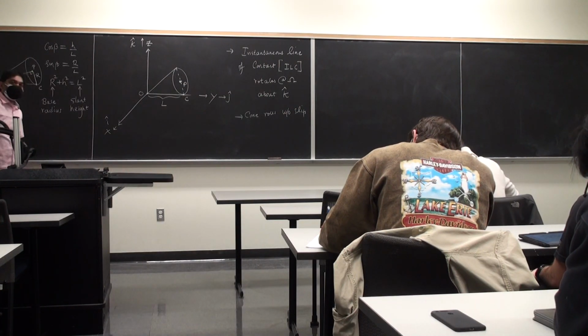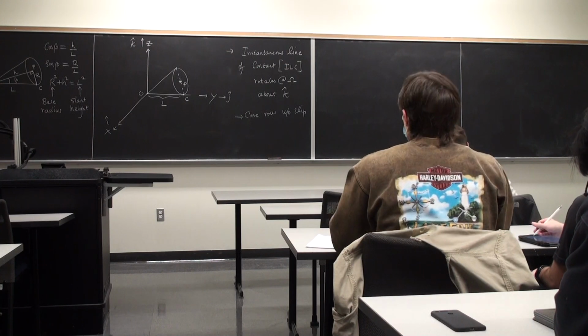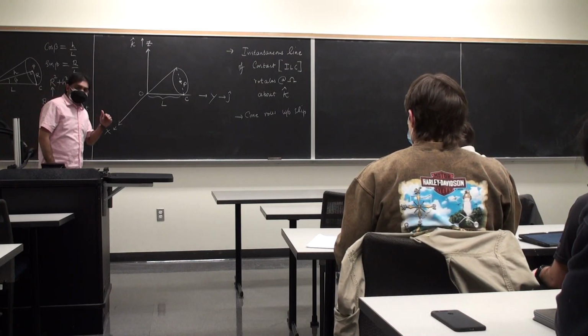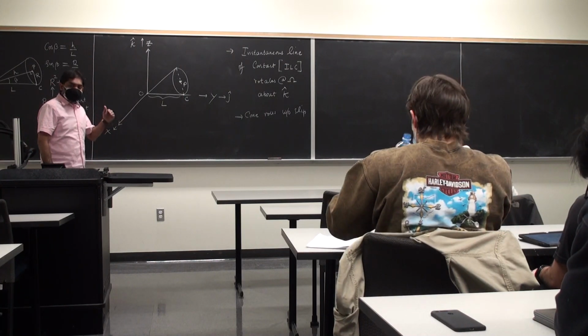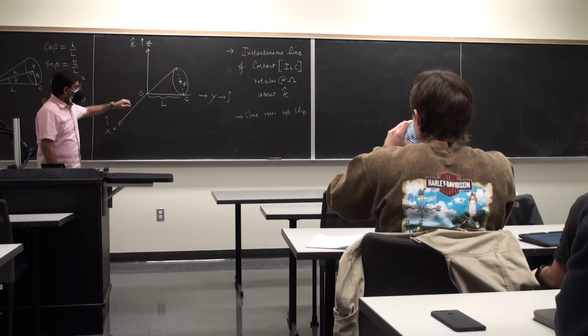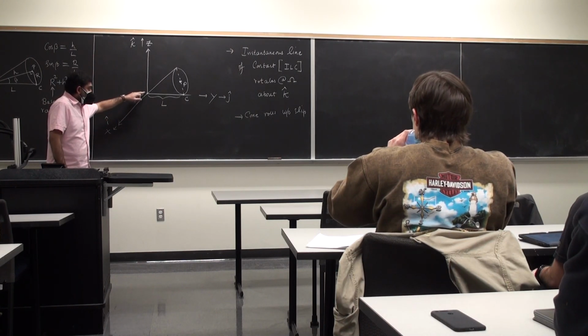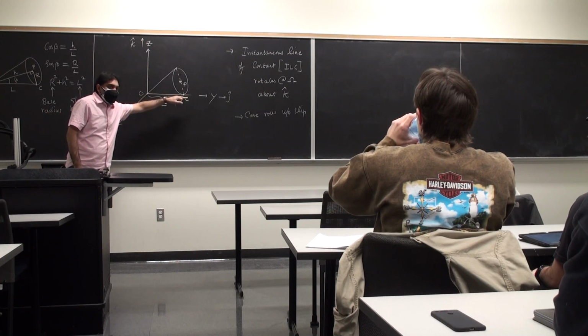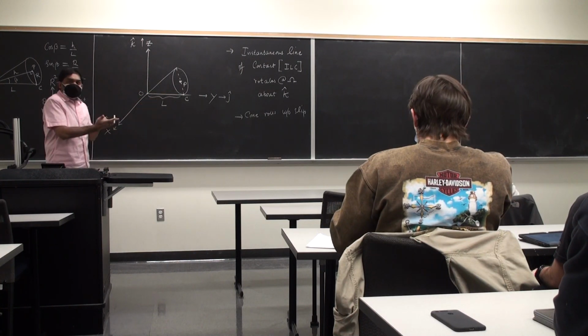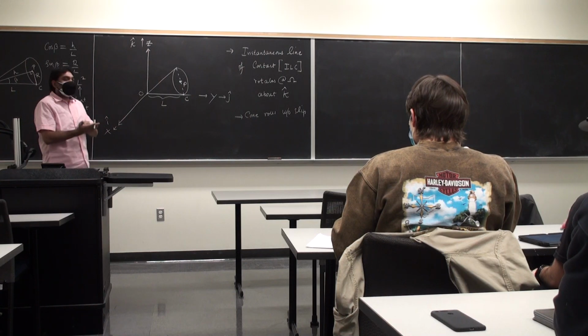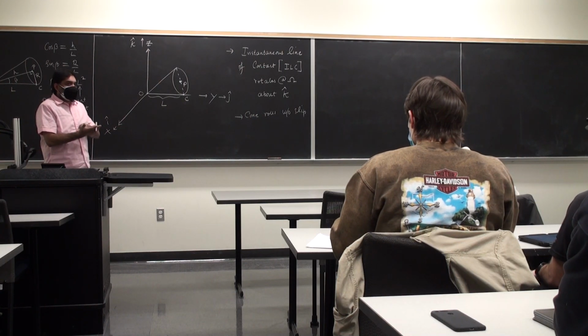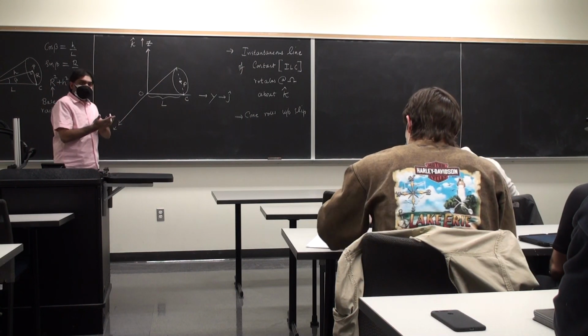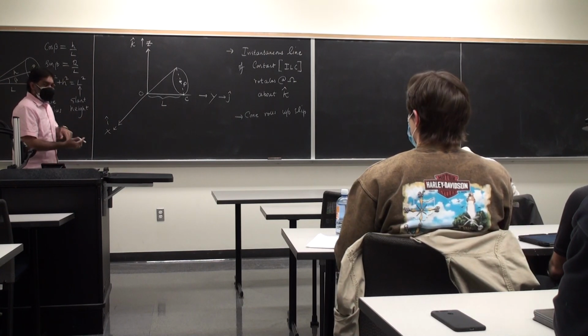The implication of that being, at any given instant in time, if the cone is rolling without slip, it means that the relative velocity between any point on the instantaneous line of contact and the plane of contact is 0. Instantaneous center of rotation is obtained in that manner.